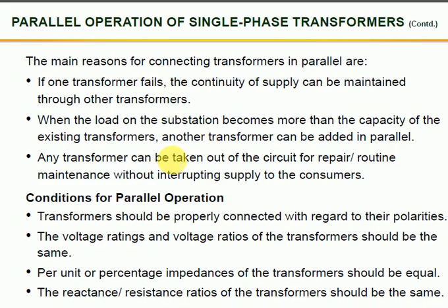Any transformer can be taken out of the circuit for repair. If one transformer is to be removed for repairing purposes, there should not be interruption of the supply system, therefore we connect them in parallel.